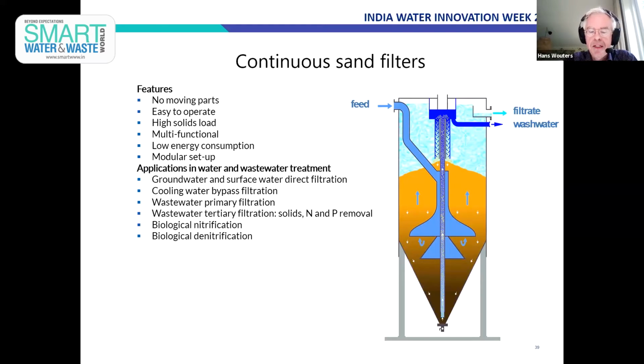And that's nice, because in this case you can use the sand filter not only to remove solids, but also as a carrier material for biomass, for nitrifying applications, for denitrifying applications, and a lot of other applications. And because of this simplicity of the process, it is a stable and robust process which will create a solution for a variety of applications. Next slide, please.